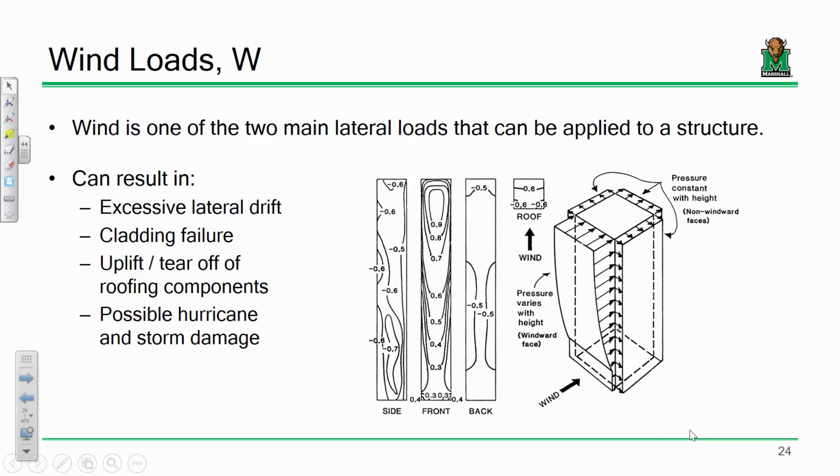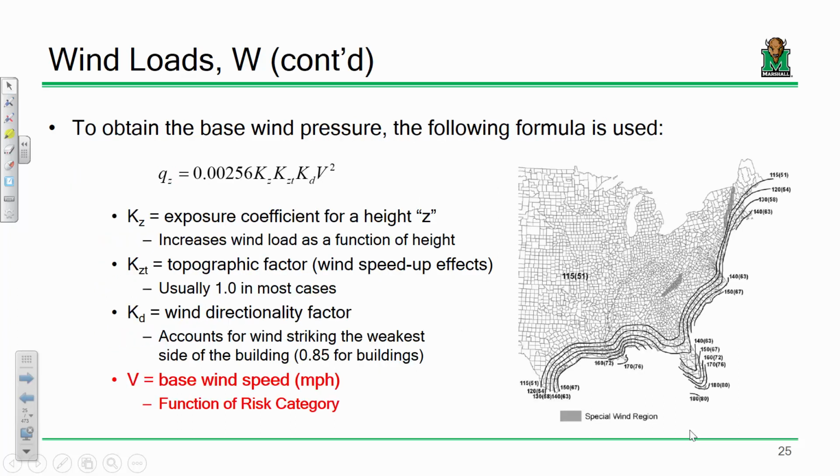We talked about wind last time. That really dominated our discussion on Wednesday. We looked at the wind pressure distribution on buildings. As the building gets taller, the wind loads increase. We talked about wind pressures on buildings and where that equation comes from. It's just a retooled Bernoulli's equation expression. Got pressure on one side, velocity on the other. Treat wind as a fluid, throw the unit weight of air in there and throw in some unit conversions, get a wind speed in miles per hour into a pressure in pounds per square foot, and there you go.